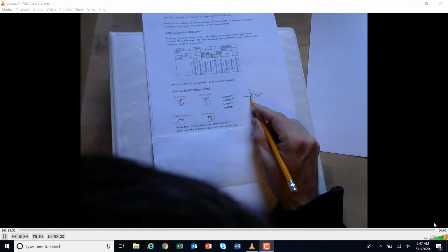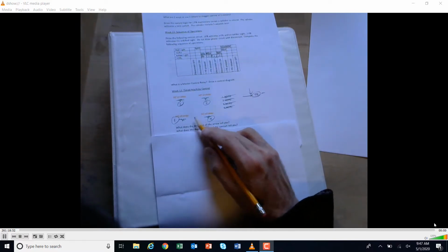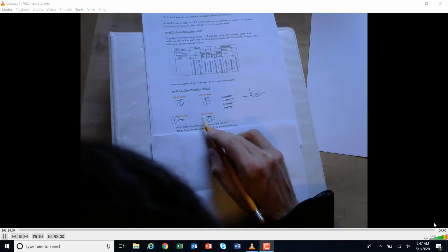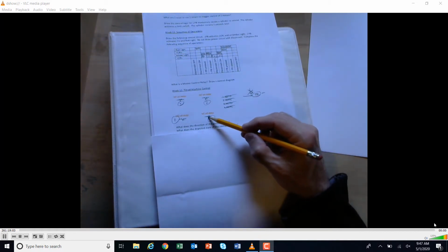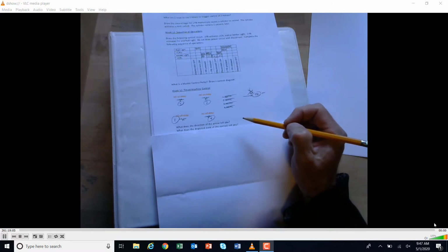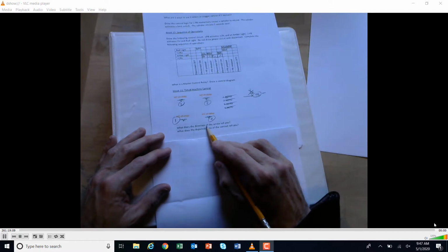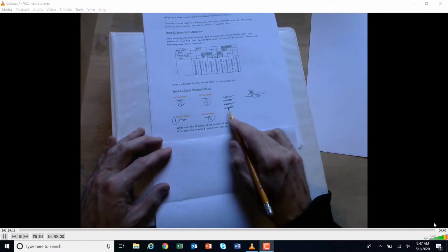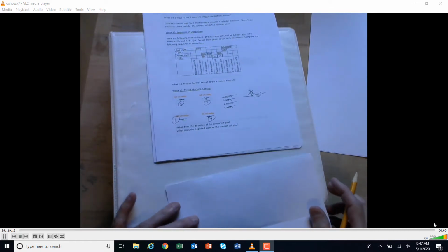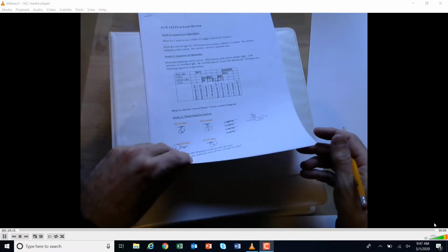What happens is when you give the voltage to the coil right there, that's when they change states immediately, but you have to then remove the voltage from that and de-energize it, and that's when they start timing and end up back to their normal position, okay? So that's the difference between those two. So that's basically, what does the contact tell you? That's the way to draw it, okay? Let's keep going here.